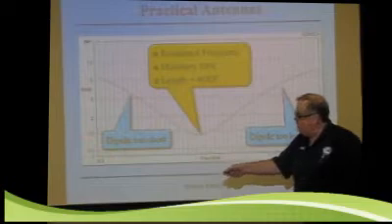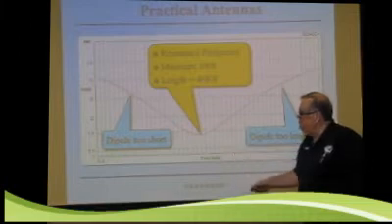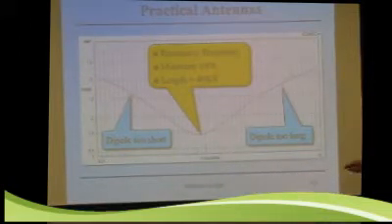as we were talking about, when you've got a low SWR, in this particular case, this is not perfect. This is showing SWR 1, 1.1, 1.5. It's barely dipping below 1.5, and it only has that one resonant frequency. As it gets further away, SWR is going to get higher. And 80 meters is particularly tough because as a percentage of wavelength, 80 meters is kind of a big band. So 500 kilohertz is a long way when you're in the 3.5 to 4.0 range.